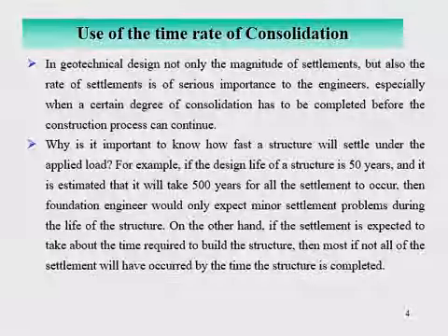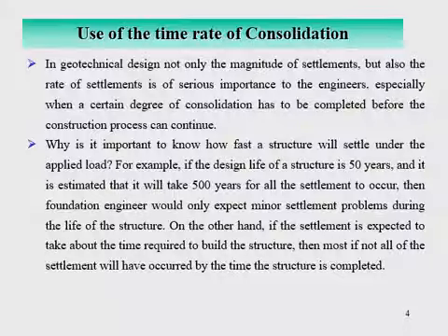Why not design your foundation or building for the amount of settlement which occurs within the design life of the structure, which is 50 years? So that's important to know when the final consolidation settlement is going to complete and occur.